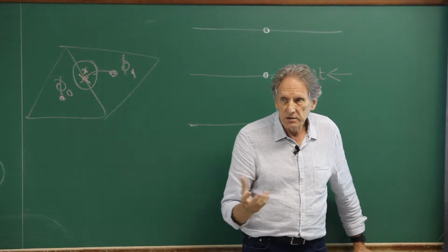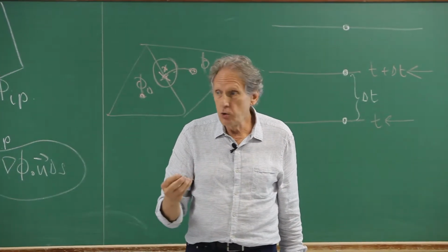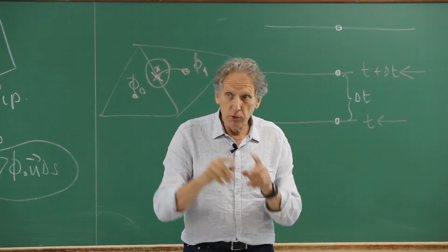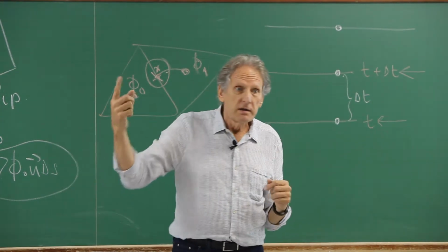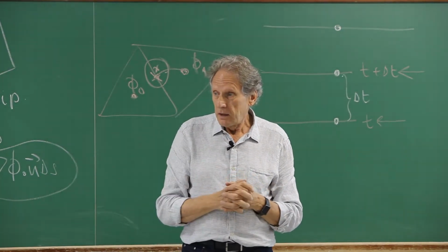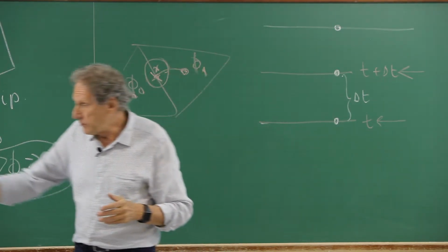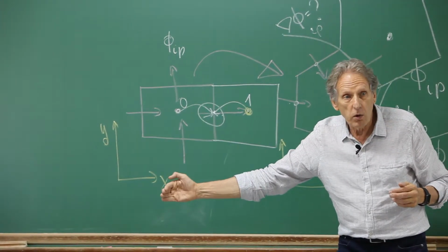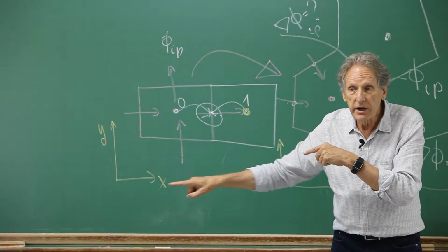Numerical simulation can be helpful even without having exact numerical values in your solution. I always try to say that if you are computing the fluid flow in this room, it's not necessary to use a very fine grid resolution at the wall, because you are not interested in calculating the gradient there.